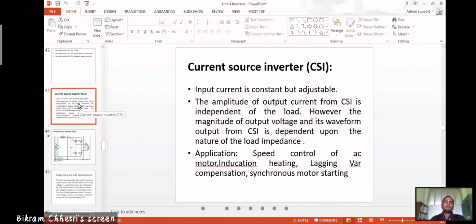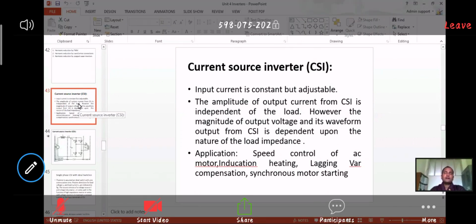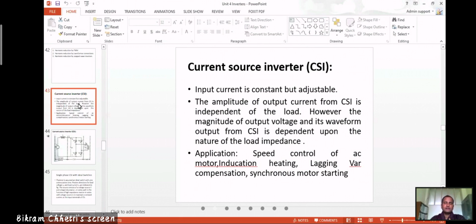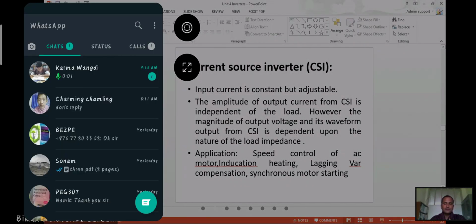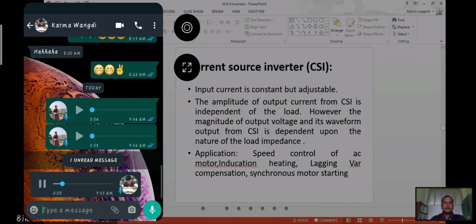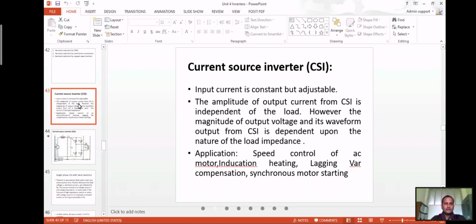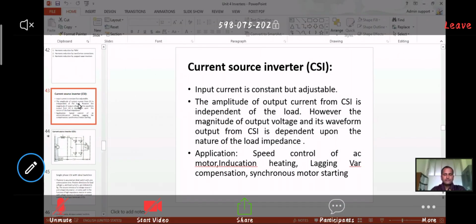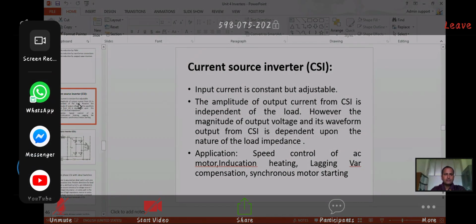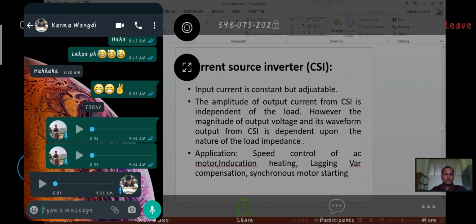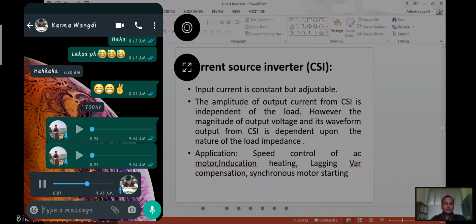We are talking about harmonics. There will be harmonics in the system, so these harmonics need to be reduced. These are unwanted signals. To reduce the harmonics, there are different ways like pulse width modulation, harmonic reduction transformers, or step wave inverters.